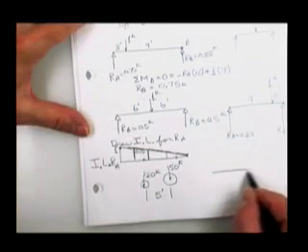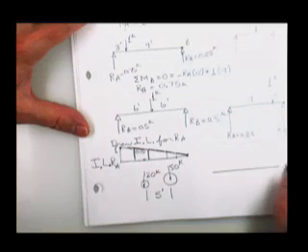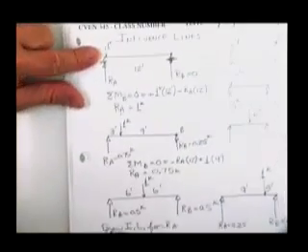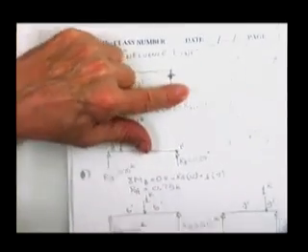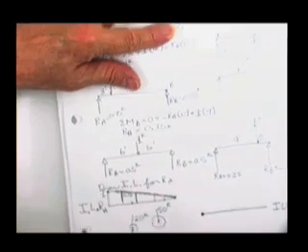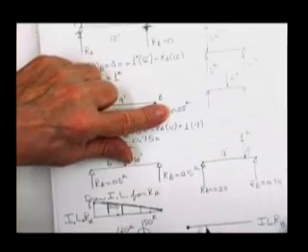Here is an influence line for the reaction at B. When you put the unit load on the left end of the beam, it causes no reaction at B. When you put the load at the quarter point, it causes 0.25.